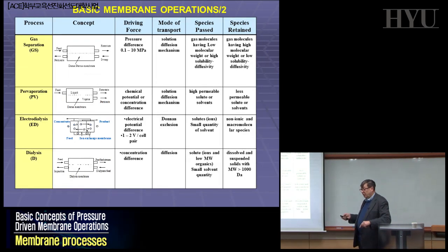These are the most traditional systems, pressure driven, utilized for the liquid phase. Keep in mind that the same methodology, and sometimes the same kind of membranes, with different polymer and different level of selectivity, can be produced with the same methodology, phase inversion, or composite materials, for gas separation.